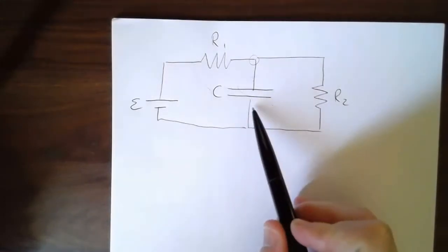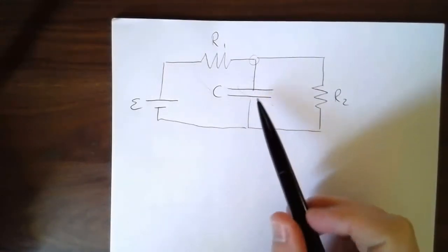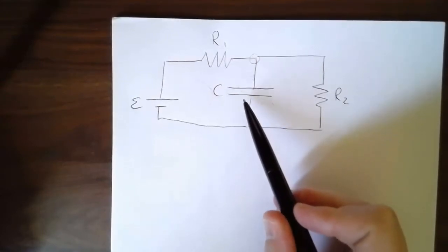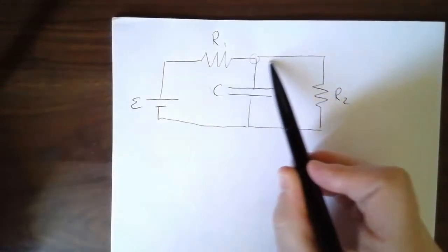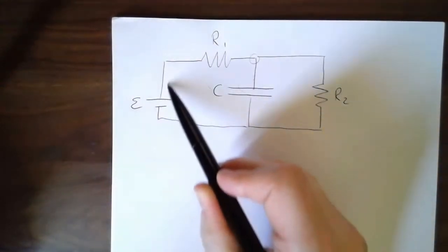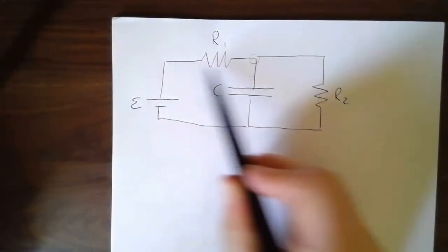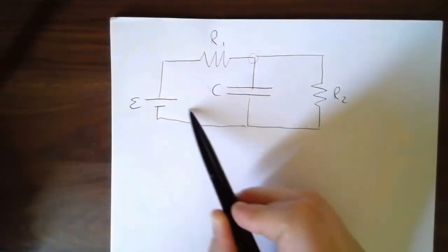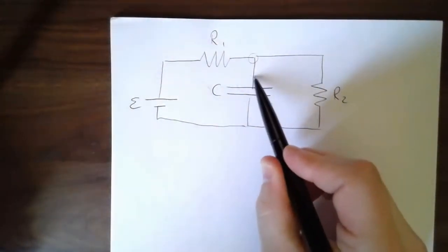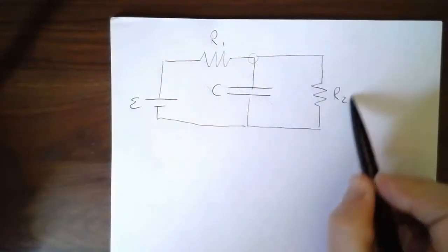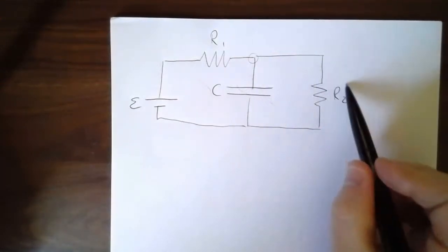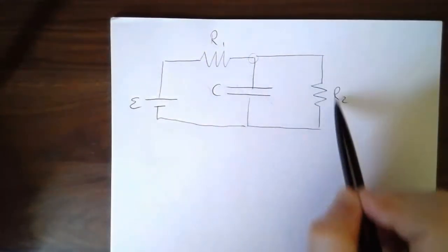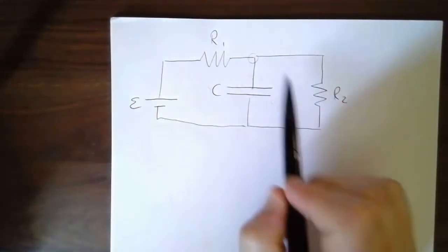What's going to happen at time equals infinity? Is charge going to continue to flow, or is it going to stop? Well, in this case, because part of the charge can go this way, it's going to keep going this way. Eventually, you're just going to have this big loop as the only part that's still moving, and the potential difference across here is just the potential difference across here, which you get from just having a circuit with two resistors in parallel. Okay, this was a lot of information, a bit of a mouthful.